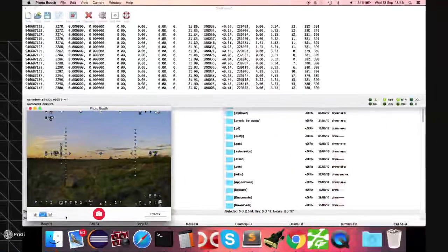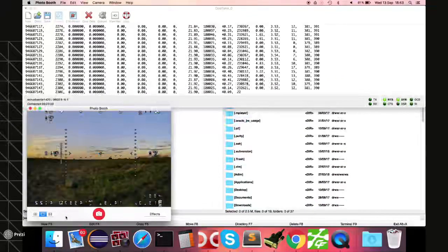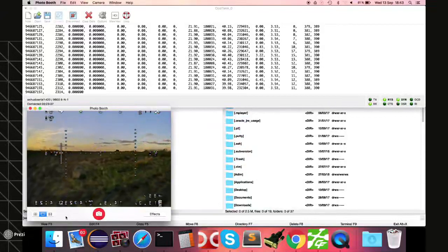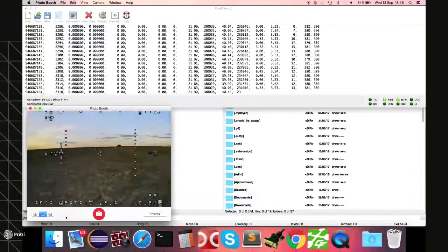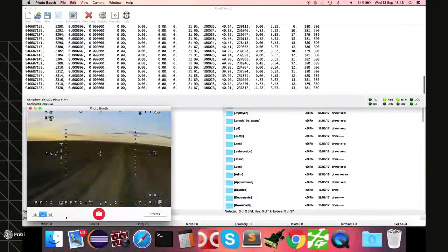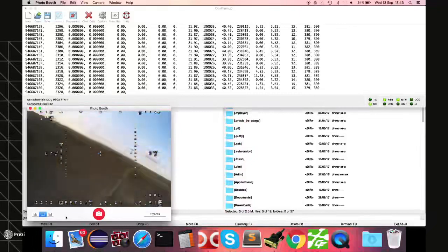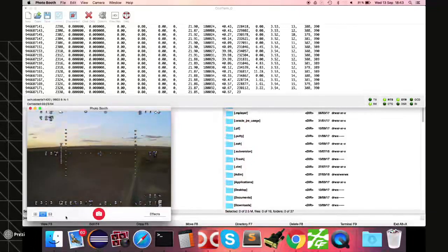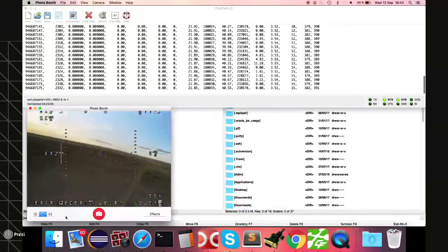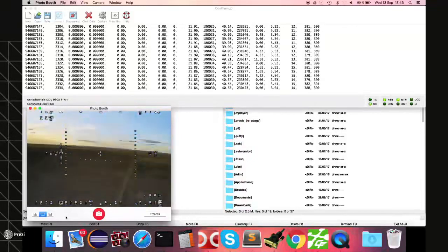You can see it in real time at the top. The data is coming to my computer via the radio link, and I'm getting it into a terminal screen. You can see the comma-separated values. I had an issue with GPS lock on the sensor board, so the first numbers are zeros instead of latitude and longitude. That's too bad, because I would have loved to see speed recorded here just for my curiosity. And then you can see video coming from the drone on the third radio channel. As I told you, it's too much. It's really too much. We need just one radio link to the thing.